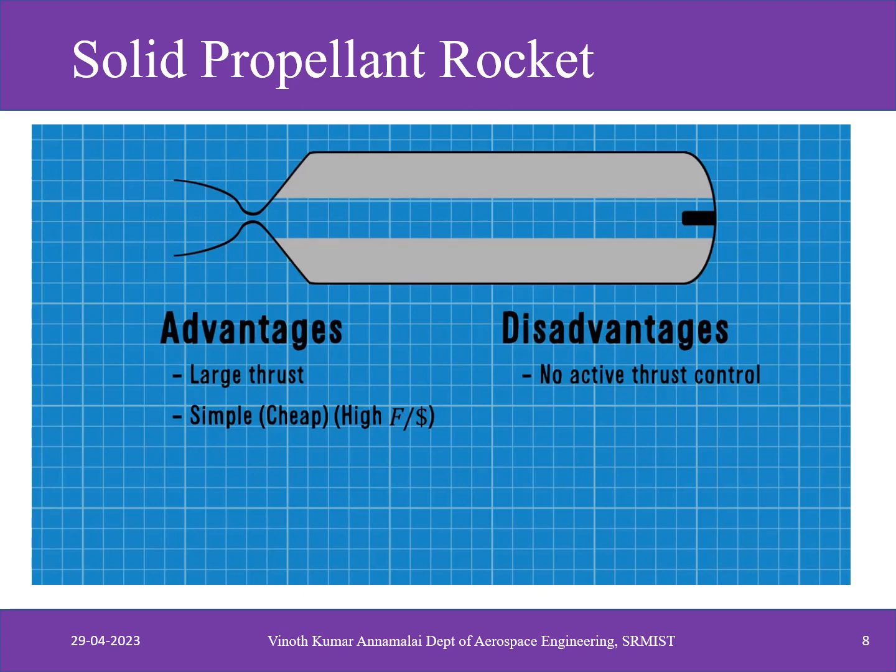Solid propellants are usually not as efficient as liquid propellants. Physically, this means that the velocity of the exhaust gas is not as high as with liquid chemical propulsion. There are no cold liquids to cool the nozzle. In liquid propulsion, the fuel is often used to cool the nozzle to prevent decomposition and for saving weight. Not having this ability is problematic for solid motors. Active thrust vectoring, actively controlling the direction of the thrust, is also difficult.